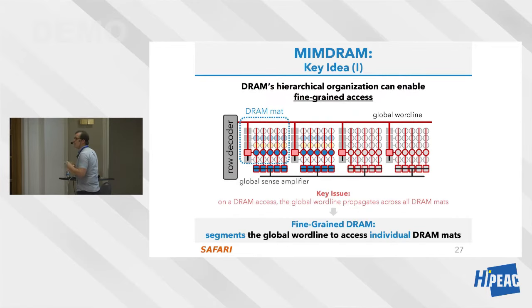So how can you get rid of this large granularity? It's actually a relatively well-known idea, but it needs to be implemented. Basically, if you look at a DRAM subarray, it consists of these smaller structures called mats. So you can see that the subarray is the entire thing over here. A mat is one portion of it. I'm showing you 4 mats here.